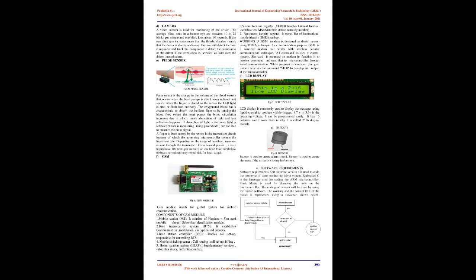C. MQ3 sensor. The MQ3 is an alcohol sensor that senses the alcohol present in the surrounding environment. There is a SnO2 element inside the sensor, which has low conductivity in clean air, and its conductivity increases when alcohol is sensed. It has good sensitivity to alcohol and less sensitivity to gasoline.